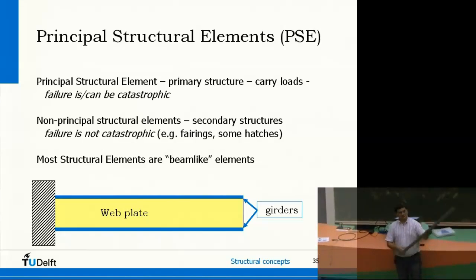This is some kind of floor beam, as used nowadays in metal aircraft. In many cases you see some holes punched in it just to reduce the weight, but nevertheless this is more or less the shape of it. You have two flanges, as you can see, and a web plate. Actually it is something like a simple beam.